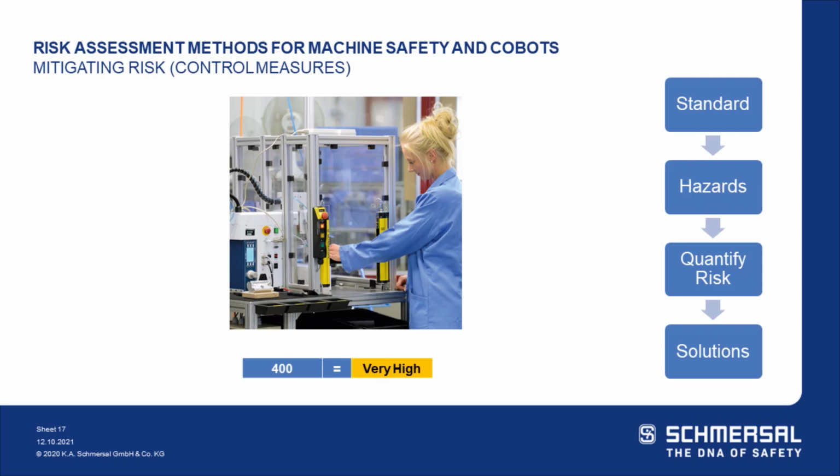Now, if the guarding you had in place works great, that's awesome, right? So in this case, they had a light curtain in place. Awesome. Light curtain's great. However, if they're putting a light curtain on, you have to determine what performance level these light curtains have to be installed to. So you have a light curtain, it solves it, but you have to determine, okay, how am I reviewing the controls drawings to determine that I indeed need a performance level D or an E? And that comes from a standard where we look at severity, frequency, and possibility. It's very similar to another risk assessment, and you come up with a letter from A to D, and that tells you how you have to have it designed.